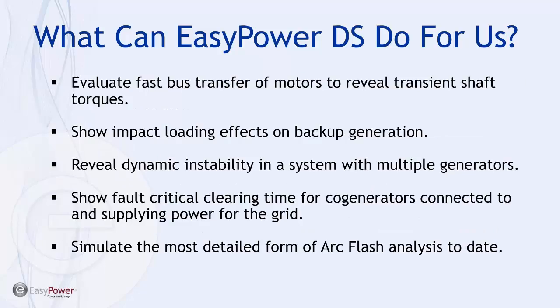Likewise, we can evaluate fast bus transfers of motors to reveal transient shaft torques. Very difficult to identify that with a load flow analysis that doesn't include some sort of a time step. Impact loading on backup generators, whether or not they can recover from the step function in the load being thrown on as a result of a fault.